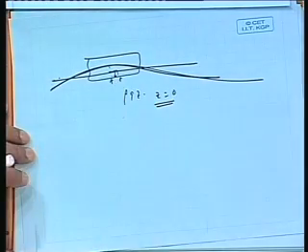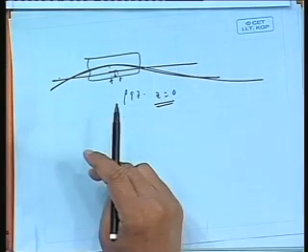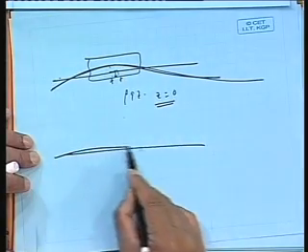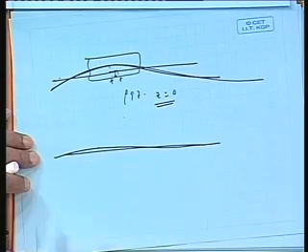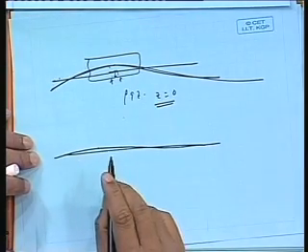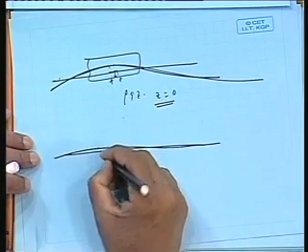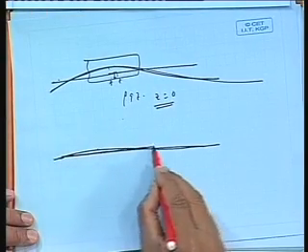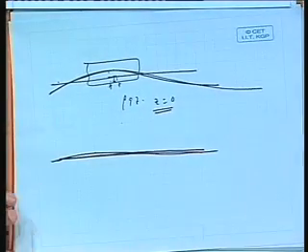This arises because sometimes the ship might have a very long wave and you may take the heights from the mean surface in a calculation. You do not normally take the height from the free surface, because typically the water is like that, and you are measuring height from this point, not from this point, because your axis is there. But if you measure from this mean line, that is the red line, then you have to take the dynamic pressure along with it. Okay, it's a very important point.